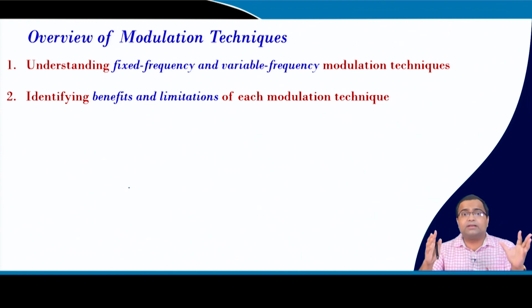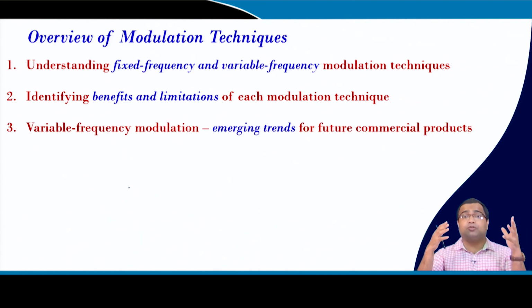So, they are very much an emerging modulation technique for wide duty ratio operation, and those variable frequency control methods are the emerging trend in power management products. I mean, power management products will probably see more use of ripple based control, like constant on time, constant off time, and hysteresis control in future. It is already there, but the majority of commercial products are still dominated by fixed frequency current mode and voltage mode control. In future, ripple based control will be dominant.